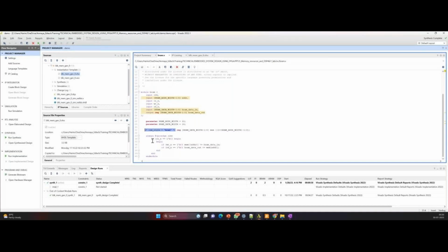What I recommend is, instead of only theoretical understanding, do you have any evaluation boards? Evaluation boards, so Virtex-6 is there, sir. Zynq board is not there. That is sufficient for the basic protocols, right? That is sufficient. What you do, you try to run all these interfaces in loopback mode.